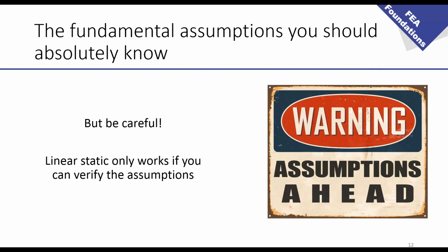Now, be careful. That's why I put a big warning. There are some assumptions ahead that you have to know. Linear static only works if you can verify the assumptions. And this is something that I have to tell several times, because a lot of people are not careful about that. They're just thinking, oh, finite element analysis is like that. So they don't know that there are more analysis types than linear static. They apply the same method to every type of analysis. But be careful, that's not true. It's only valid when the assumptions are validated.